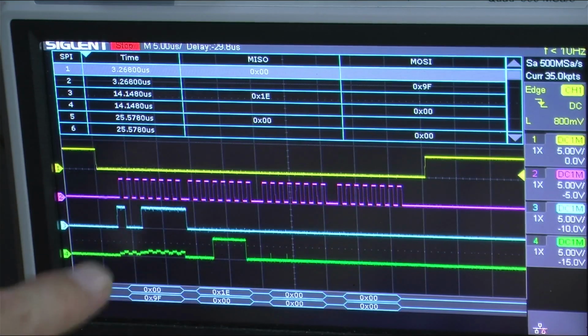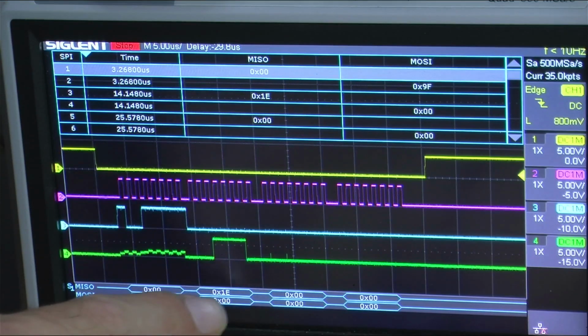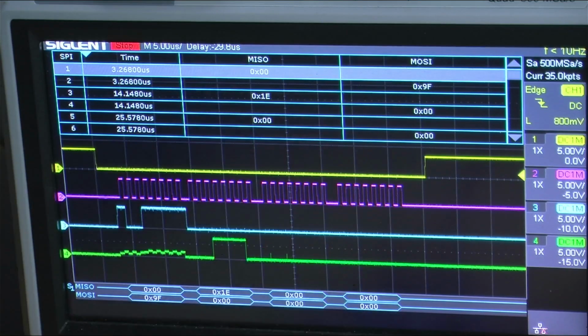So in this instance, because we're transmitting the first byte rather than receiving anything, we'd actually just be ignoring this noisy bit here, and then we'd be listening to the data that's coming back on the remaining 3 bytes that we've got there. So that's kind of what those signals look like. Gives you a bit of an idea of how they work. So let's jump into some code and let's see how we actually make that work with our STM32 device.